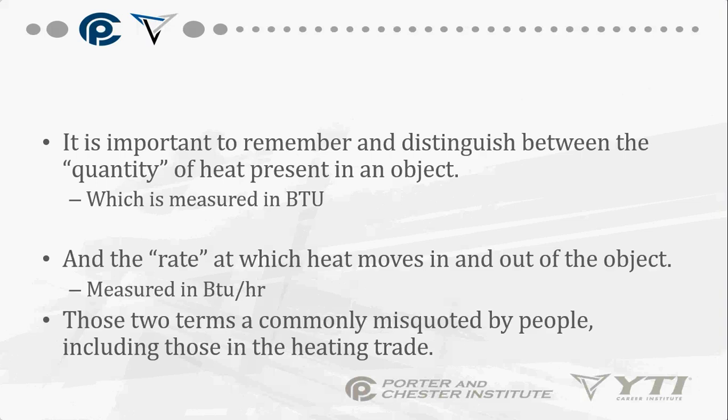Okay, it is important to remember and distinguish between the quantity of heat present in an object, and that's measured in BTUs, and the rate at which heat moves in and out of the object, and that's going to be measured in BTUs per hour. Okay, those two terms are commonly misquoted by people, including those in the trade.